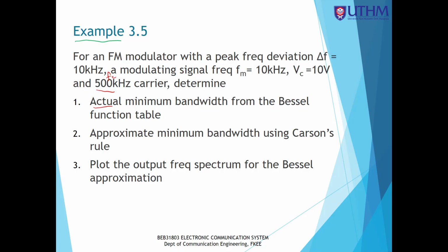In order to find the Bessel bandwidth, remember bandwidth by Bessel is equal to 2 times n times the modulating signal frequency. So how much is n?